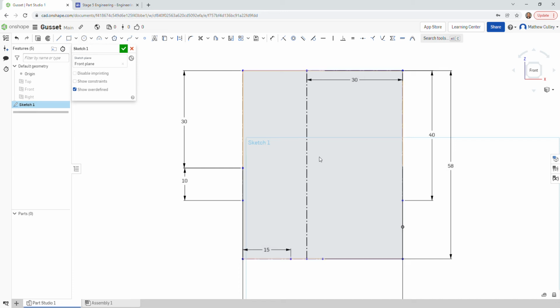Then going to do another construction line. Okay, you'll notice there's quite a few construction lines to get this set up. It looks a little bit messy, but we'll delete all those lines in the end. So click on the top right hand corner, come across, I want to come across 10 millimeters. Left click, type 10, hit enter, escape.